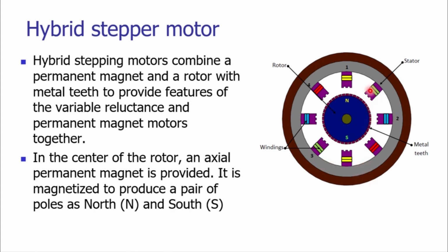These poles have windings, but here you notice there is a peculiarity: the stator poles also have teeth. The number of teeth or poles are provided to have finer adjustment in the increment of the rotor.